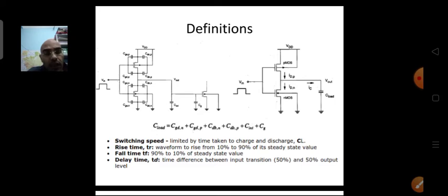The circuit will feel some impedance. That opposition to the current will not be because of the inductance but because of the resistance of the running wires, the interconnects, and the devices themselves. So there will be some resistance and capacitance. The propagation delay basically comes from this RC circuit, which forms because of our devices and the parasitic capacitances of the device, the next stage, and the interconnects.